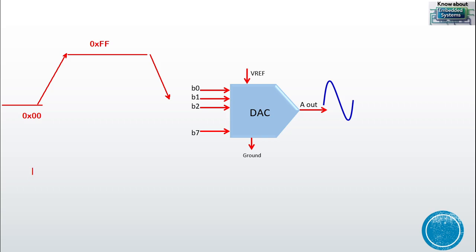To do that, we can use one for loop for the positive ramp. When it reaches the 255 value, add a small delay, approximately, based on requirement. So, positive ramp, and when it reaches 255 you add some delay here, and then for the negative ramp we have to use one more for loop.